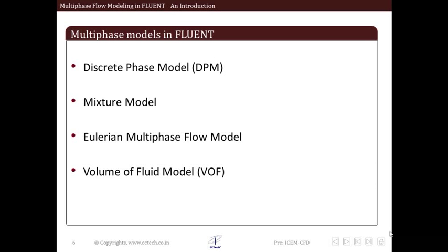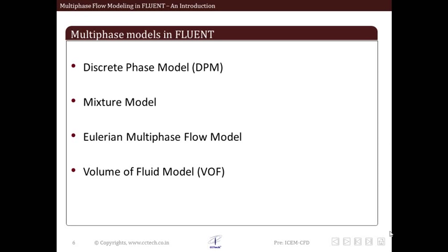So as we have seen different types of flow regimes under multiphase flow, now we will proceed to multiphase flow models in FLUENT. Do keep in mind that in this particular lecture, which is an introduction to multiphase flow modeling in FLUENT, we are not going to go into depth into all these models. What we will see is how to activate multiphase flow in FLUENT, and within each panel of multiphase flow settings, how to input different parameters and what types of such inputs and panels are available in FLUENT to model multiphase flow. So this is just like a primer or an initial overview of multiphase flow modeling in FLUENT.